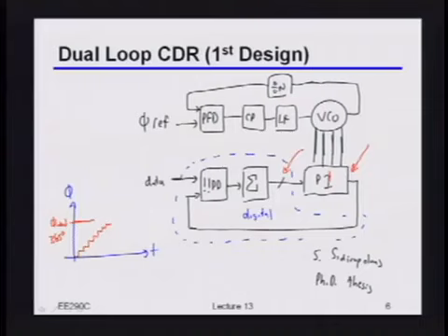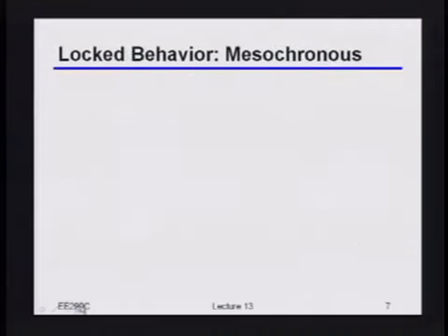So that always implies, of course, that if there's a finite resolution with which I control that phase interpolator, you can never get exactly the right value for the phase, right? All you can do is get close to that value and then jump around in that vicinity, right? So what I'm implying here is that, as an example, let's think about a